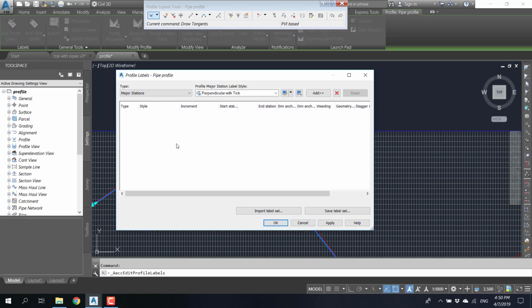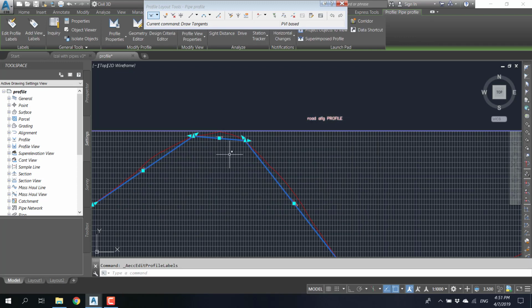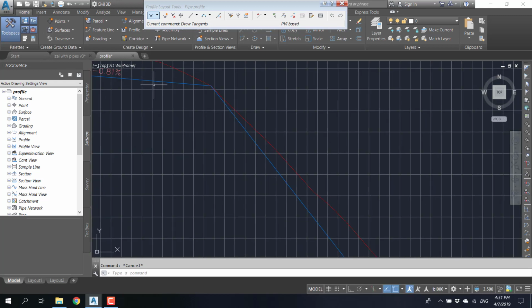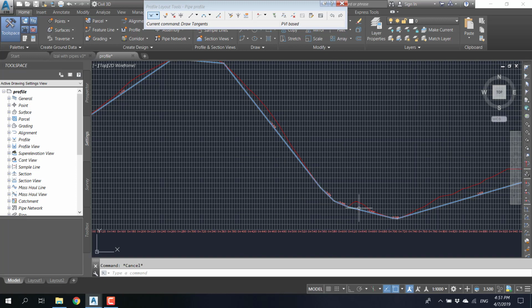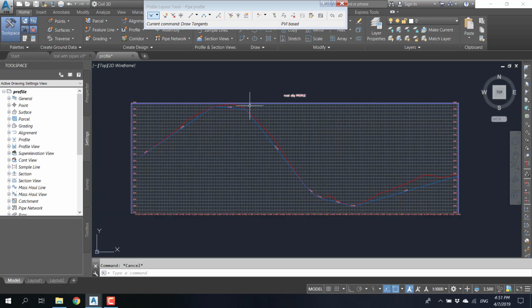We have removed this. Now, after you enter the profile labels, type select lines, slope 1 in X or %grade. You have 2 options or formats for the slope. I prefer the %. Add. Okay. Now it's added. Now I want to offset the pipe profile by 1.5 meters below ground.